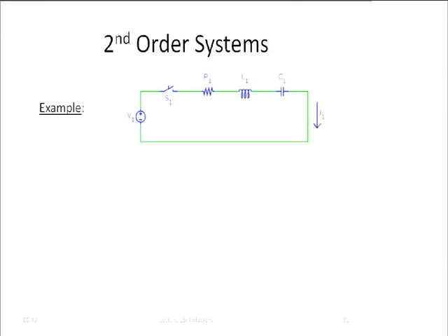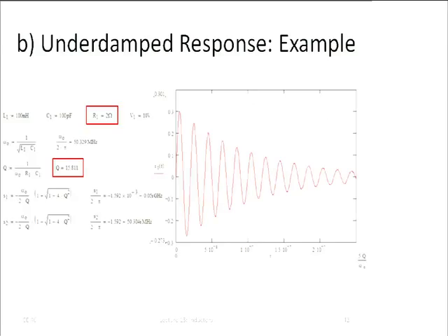Before we've looked at when we have a first order system, just an inductor, just a capacitor, then we get some kind of an exponential decay, right, when we hit it with a step. So we turn on the voltage, and then the current goes up, and then the current decreases. And if we have a second order system, much more complicated stuff can happen.